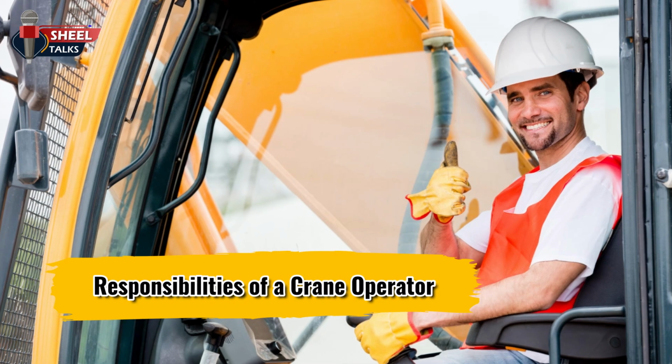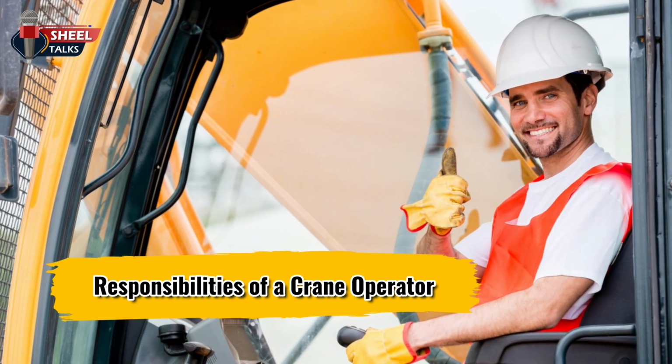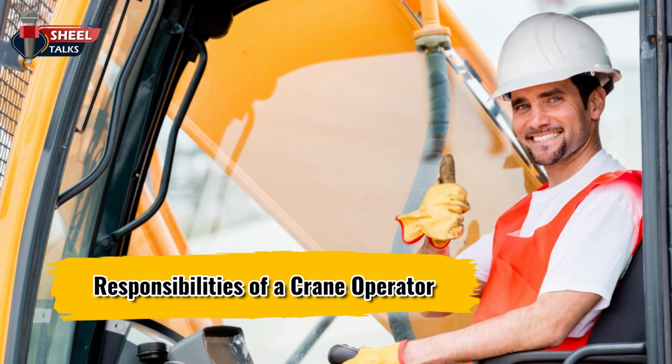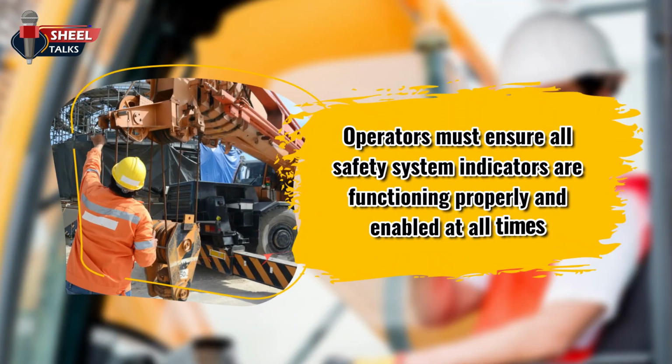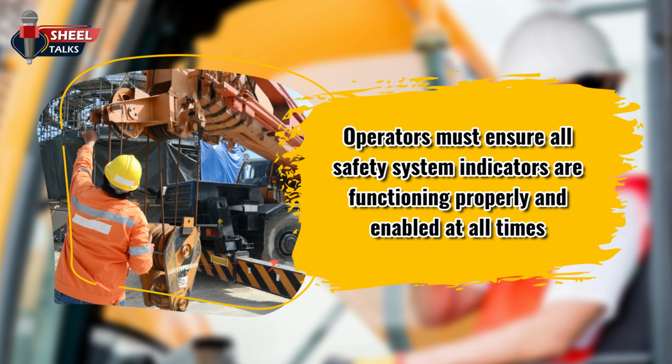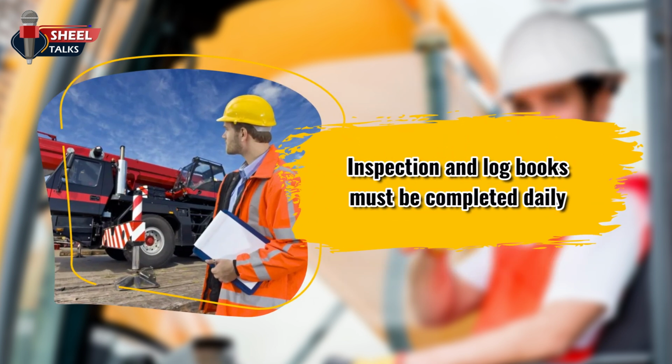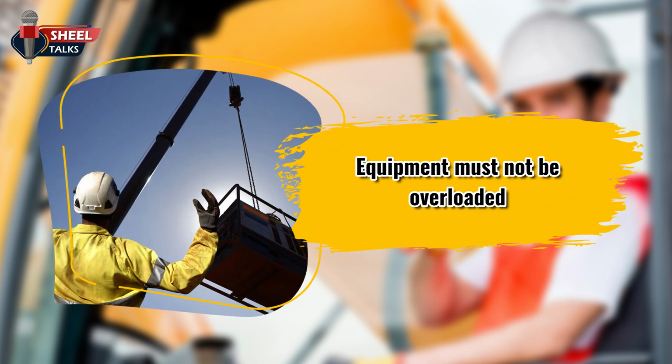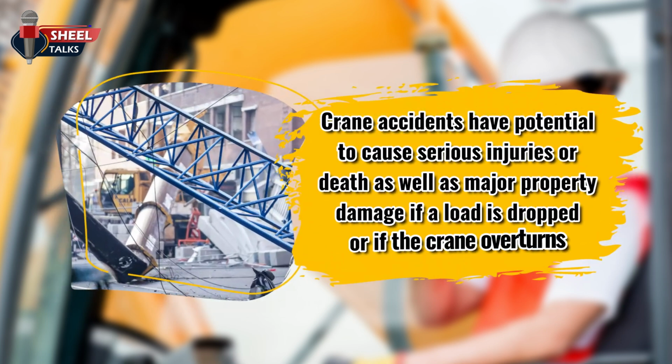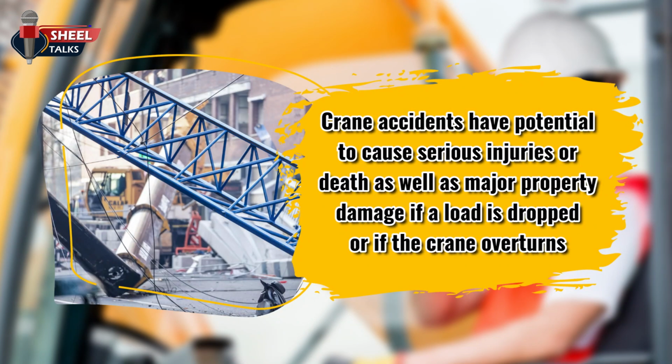In order to minimize the risk of accidents, let's discuss the responsibilities of a crane operator. Operators must ensure all safety system indicators are functioning properly and enabled at all times. Inspection and logbooks must be completed daily. Equipment must not be overloaded. Crane accidents have the potential to cause serious injuries or death, as well as major property damage if a load is dropped or if the crane overturns.